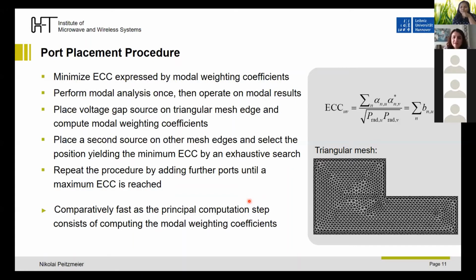Based on the numerical examples that you showed for asymmetric antenna, in order to find the proper semi-uncorrelated ports, in my opinion, we can conclude that CMA doesn't really help us to give an insight for asymmetric antennas, because at the end you are doing some optimizations in a blind way in order to find the uncorrelated ports, and then you're not really benefiting from the CMA to give you some insight about the modes. Do you have any comments about this?